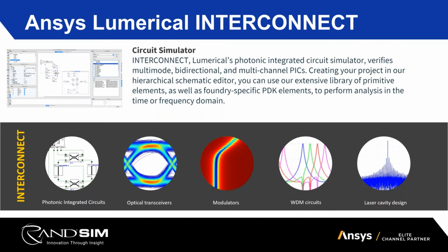Focusing a bit more on Lumerical INTERCONNECT, this is basically the complete design package for making photonic integrated circuits. In the circuit simulation, we have both frequency and time domain simulation. They both support bidirectional and multi-mode circuit topologies. We also have the built-in element library, which has all the necessary components you would need to build one of these circuits, such as sources and analyzers. It also includes some electrical elements for active component simulations.